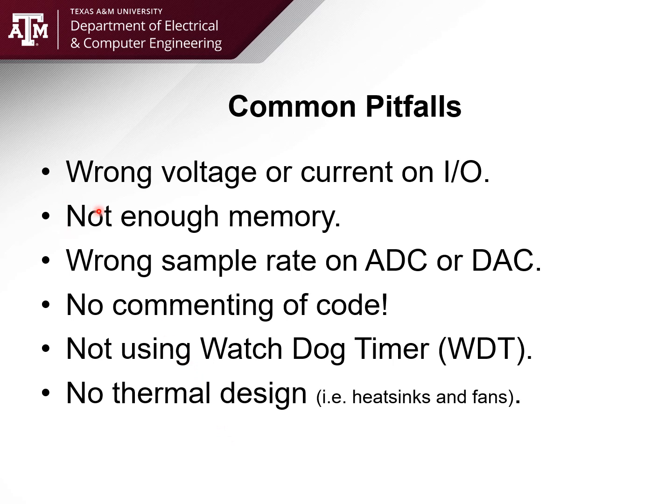Wrong voltage or current on I/O pins. Again, a lot of this, I/O pins on the microcontroller are at a certain voltage. Say it's 3.3 volts. If I try to connect a 12-volt device to my 3.3 volt I/O pin, 12 minus 3.3 divided by 0 is a problem. Ohm's law, but doesn't matter there. So making sure that we have the right voltages and currents being supported in the I/O pin.